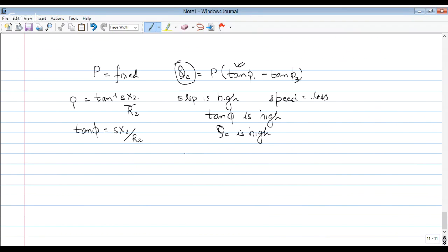Actually, a capacitor start motor increases the starting torque by increasing the angle between the auxiliary current and the main winding current. But why would it reverse its direction? So Naveen, this question is not quite clear to me because I don't see any reason why it should reverse its direction.